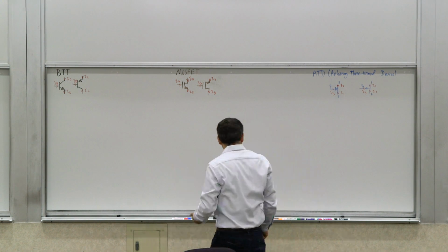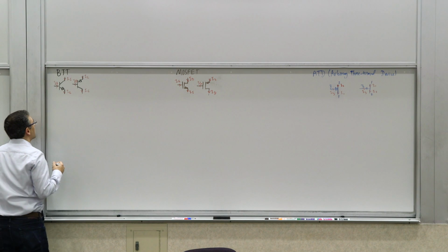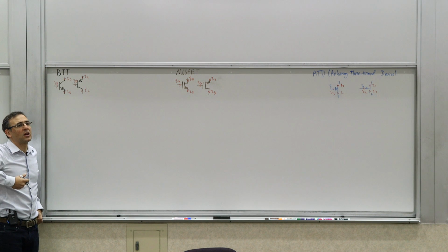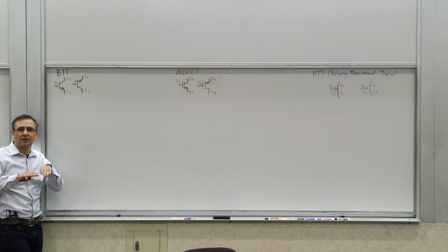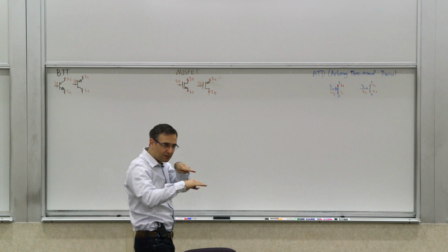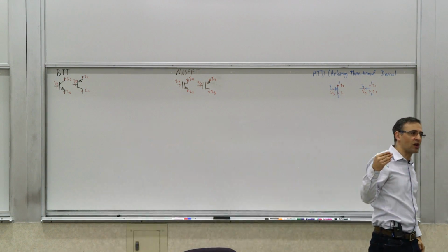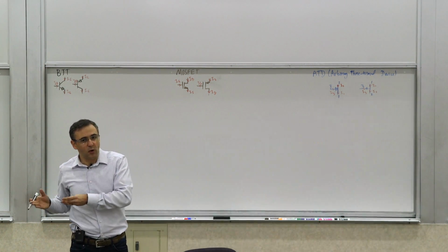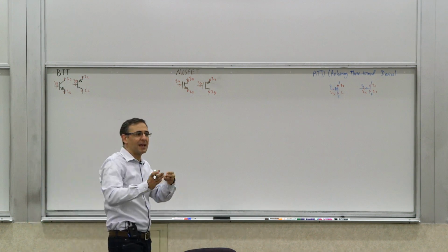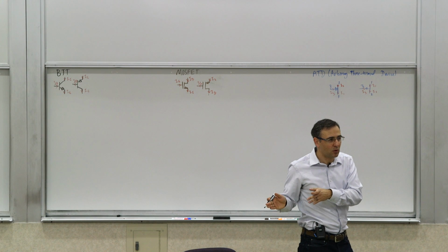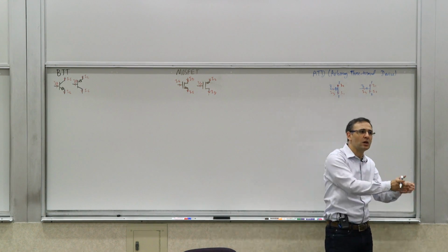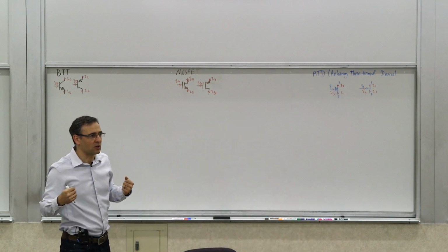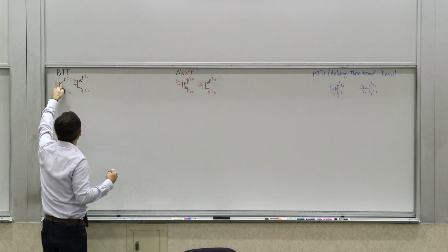Now, let's go to the bipolar. Let's start with the BJT. So what is the first order behavior of the bipolar? What is the part that's particularly useful? We know that because of the potential barrier adjustment, it's a thermal device. You lower the potential barrier between the base and the emitter. And what happens is that more charge carriers, in the case of an NPN it would be electrons, in the case of a PNP it would be holes, flow from the emitter through the base. And once they're in the base, due to the random thermal movement mostly, and some other secondary effects, they make it to the collector. Once they're at the edge of the collector base, there's an electric field that sucks them in, and they form the collector current. So that would be this flow.